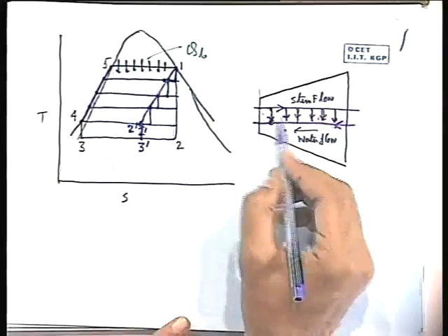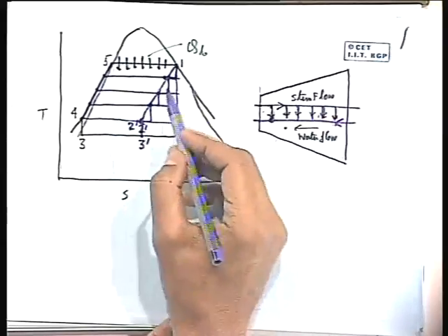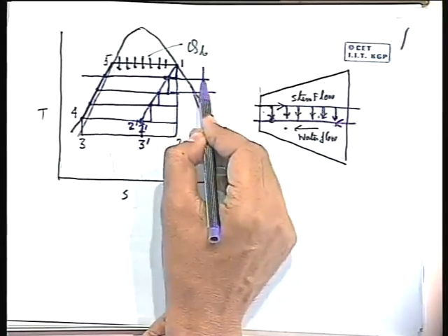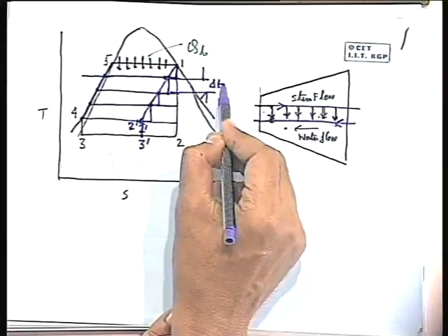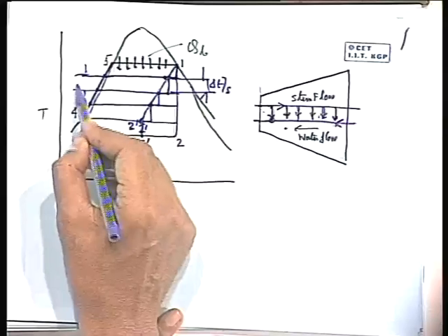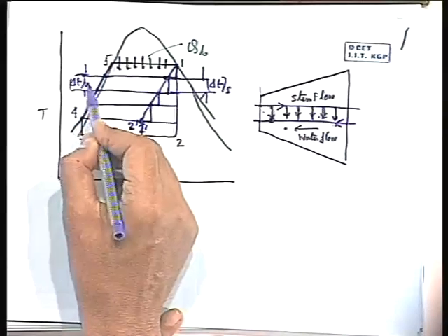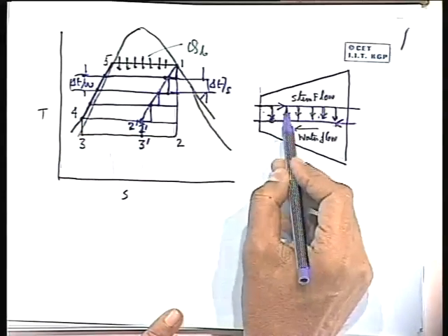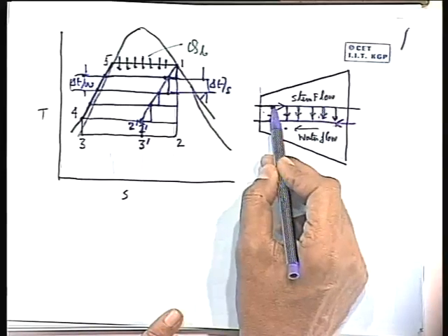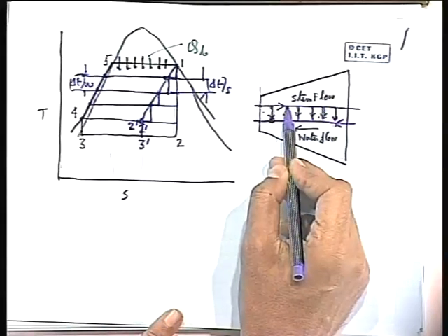Now you see the delta T is very small. So at each and every step, let us consider these two steps. The rise in delta T on the steam side becomes equal to this delta T on the water side. Obviously, because this delta T is the same. That means the temperature rise for the water will be equal to the temperature rise for the steam.